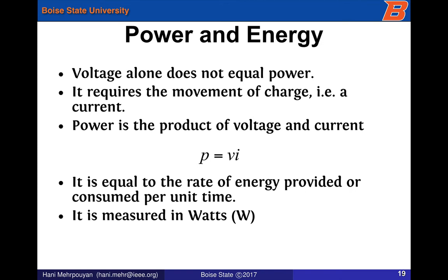So please remember that voltage alone is not equivalent to power. Voltage is the potential to do work. It's exactly the same as having a ball that sits at a higher altitude or higher point. When the ball is sitting, it's actually not doing any work, so it's not exerting any power, it's just sitting at a higher potential. So you need moving charges, a moving ball, for example. If we use the gravitational metaphor, then you need the moving charges to actually exert power or generate power.